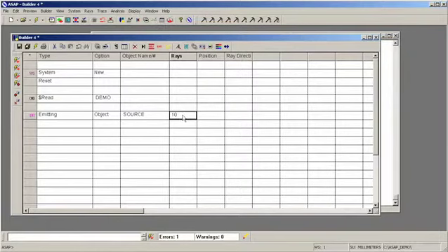The parameter on the right is the number of rays. I'm going to use the default here. Now, one thing we need to keep in mind is that ASAP is a surface modeler. Any surface has two sides. ASAP does not know beforehand which side is best for the user's application. It might decide to emit rays from the inside or the outside, or in the case of a plane, from the left side or the right side. So what we normally do here is we come in with a small number of rays and we confirm whether or not ASAP has made a reasonable choice for our application.